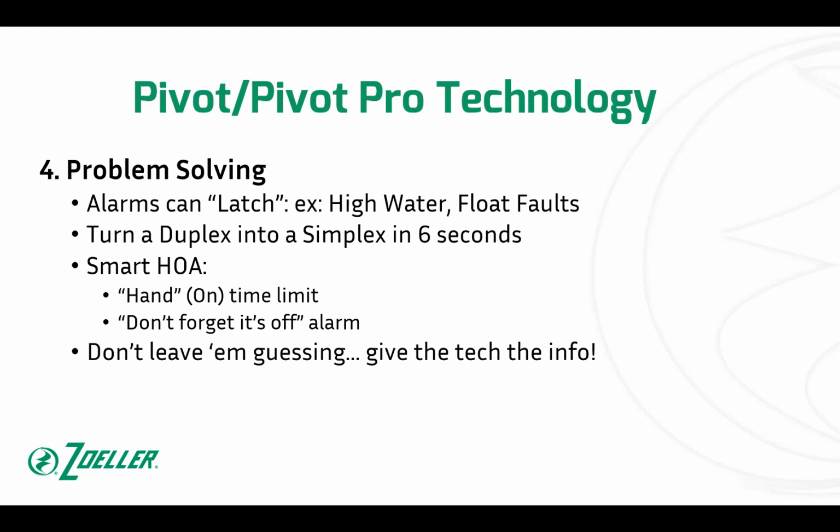And now that service off blinks, and my little label there says, if it's blinking, it's in permanent off. That just means I'm not going to get an alarm. And that's good, because if I know I'm going to be gone for a couple of days getting a pump or a part or whatever it is, I don't want the property owner to get an alarm. So I can avoid that phone call. But I had to do it intentionally is the point. I had to hold it for 6 seconds. So we want to make sure that we're not leaving these contractors, the guys in the field that are having to take care of this, guessing. We want the tech to have info.